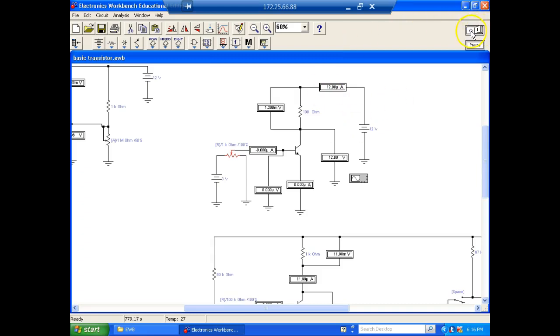Okay, I'm going to turn it off and turn it back on. And we look at our collector current right now. So notice on my base I have 0 volts. So the transistor's cut off. And up here on this meter it's showing 12 microamps, which is basically nothing, right? And a transistor is never ever truly off because there's a path current can get through there. So we'll always have a leakage current through the transistor, just like a diode when it's reverse biased. There's a leakage current through there. But it's going to be so small it's not going to do any work, right?